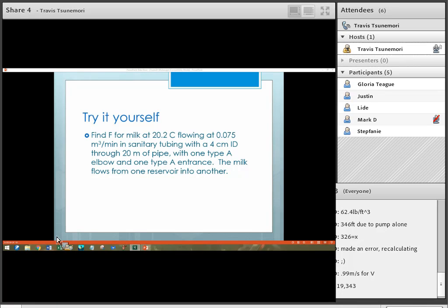Yes, 19,343. Great, that's your Reynolds number. So then you're going to want to calculate your friction loss in your pipe.